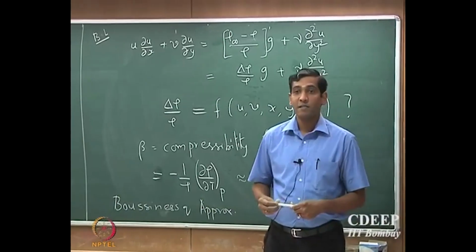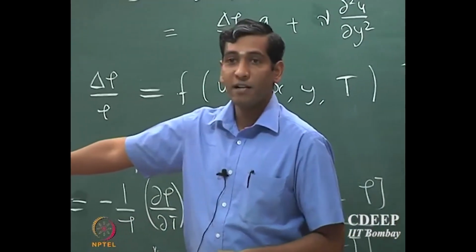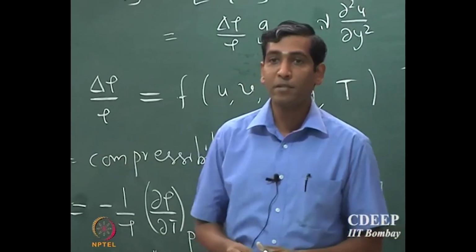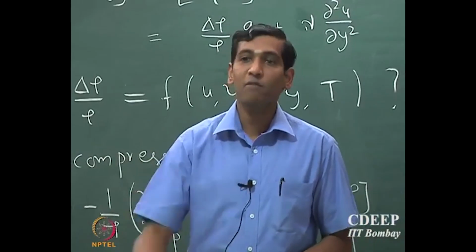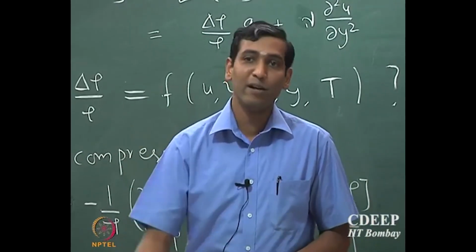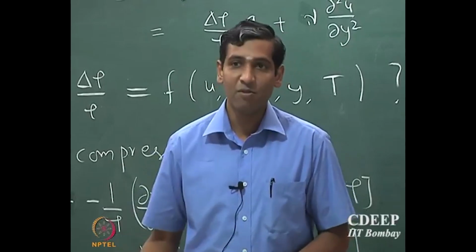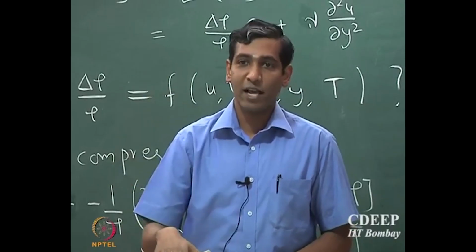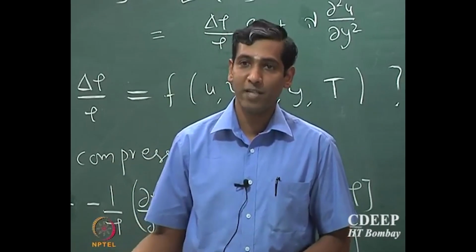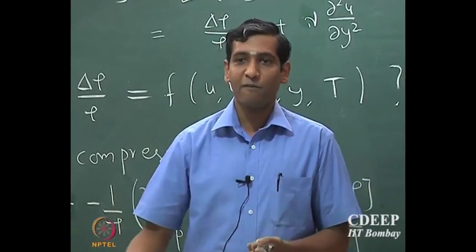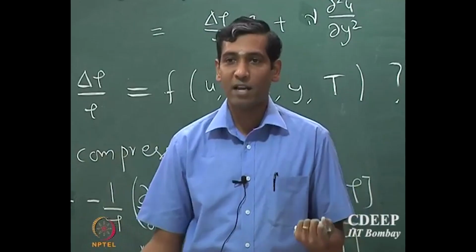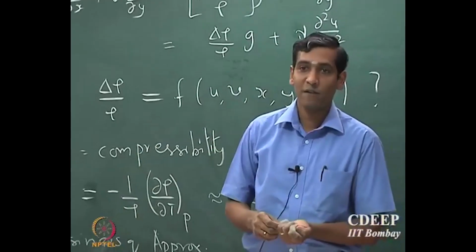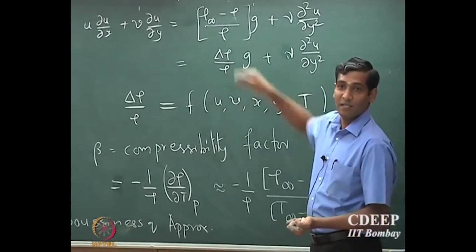Yes, Saransh. That comes from the relationship between the pressure gradient in the quiescent region. So if you write the momentum balance in the quiescent region, where there is no velocity, velocity is 0 because the fluid is at rest, and the velocity gradient is 0. So therefore you will see that the x momentum balance will simply reduce to the pressure gradient in the x direction being equal to minus rho infinity times gravity. And because there is no external forcing, the gradients have to be equal in the boundary layer and the quiescent region, and therefore you replace the dp by dx with minus rho infinity into g, and that's how you get this expression. Okay.